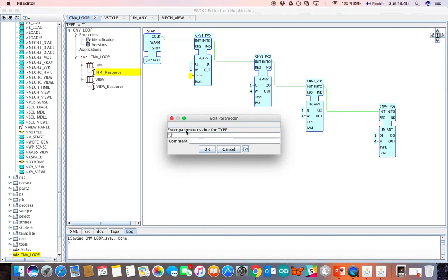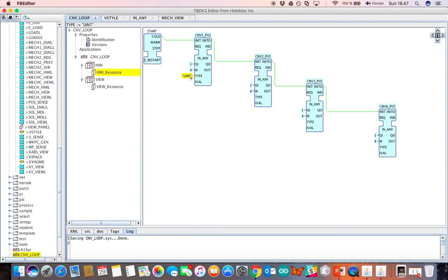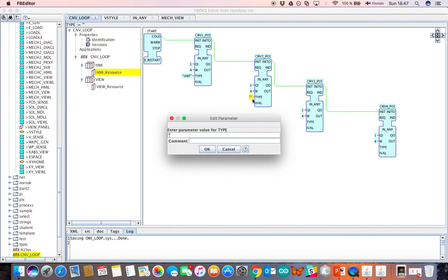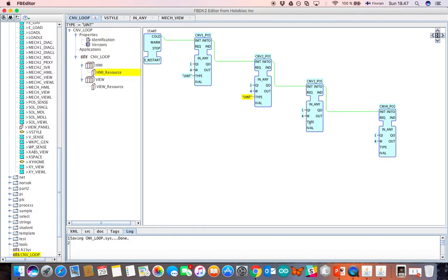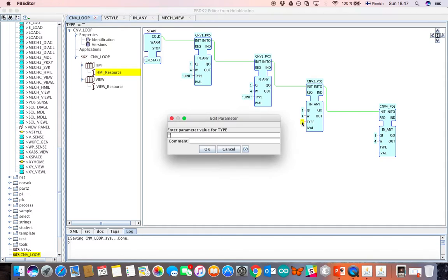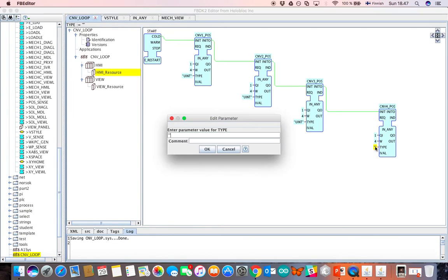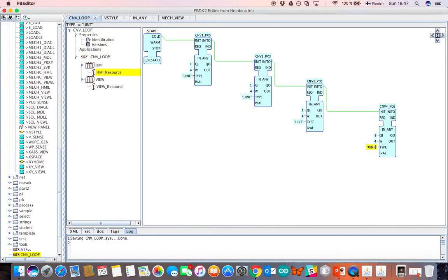In the quotation marks, I enter uint. So this is information we received from POS type uint. Since we would like to provide the position for this conveyor segment, we need to specify the corresponding type. Again, this applies to all the other blocks, as all of them provide position. If you needed a boolean, you would type bool there, but in this case uint goes for all the blocks.